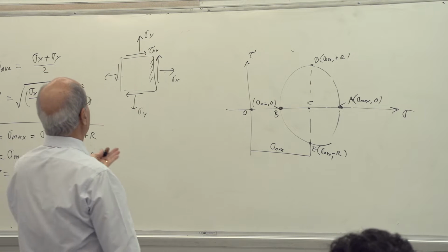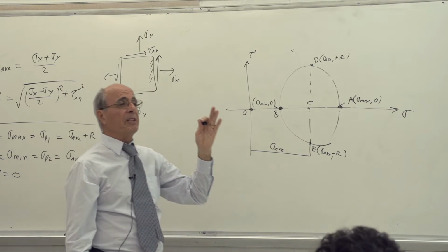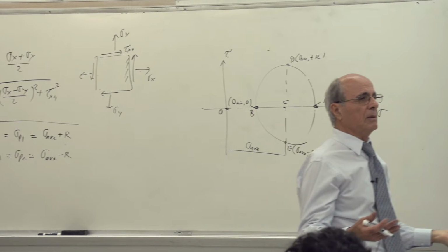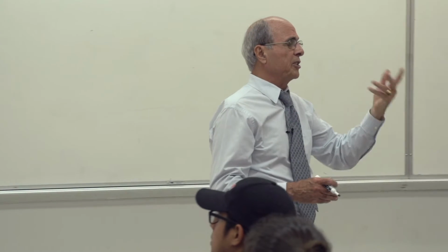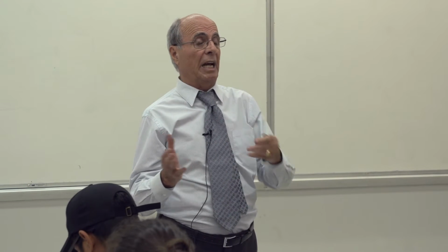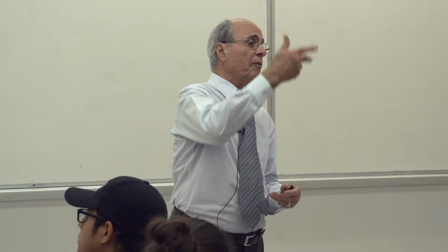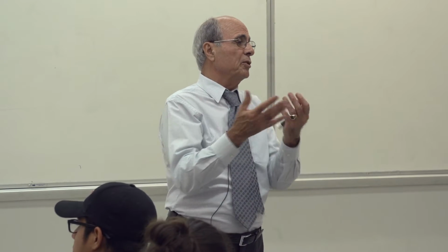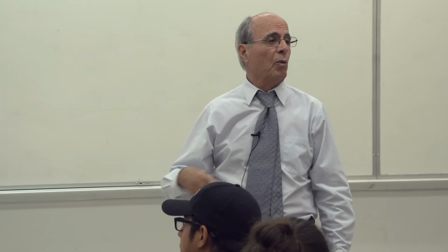In the drill, I gave you the state of stress. Then I went 22.5 degrees, all the stresses changed, yes or no? Some of them got larger, some got smaller. I believe sigma became larger and the tau became smaller for that particular problem. Then we decided, okay, as I go along this way 22.5 degrees, since it is changing, maybe if I go 32.5 degrees, I get to the highest value. So the next question you want to answer here is, where are they?